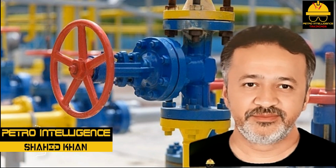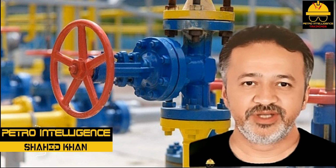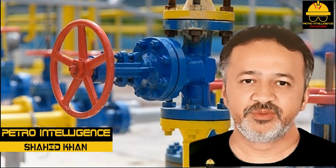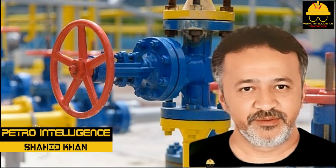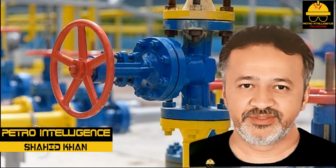Bridge wall markings. The body of the valve contains bridge wall markings, which provide manufacturer information specific to the valve. The bridge wall markings include the following letters and symbols. W indicates low temperature water service. O indicates low temperature oil service. G indicates low temperature gas service. Arrow indicates flow direction. Additional information on size and pressure rating is sometimes found on a plate attached to the handwheel.